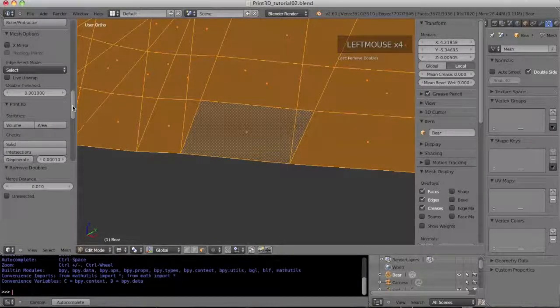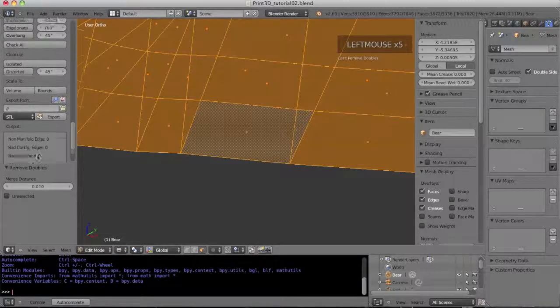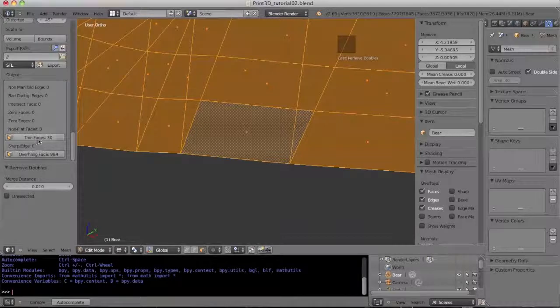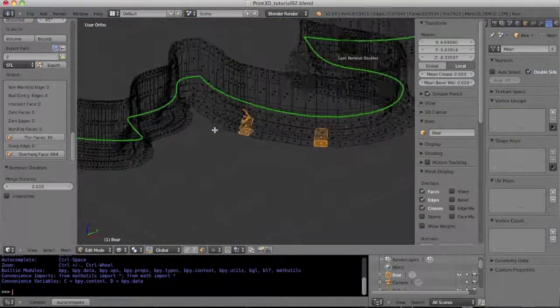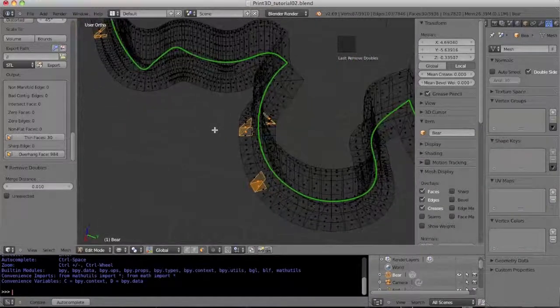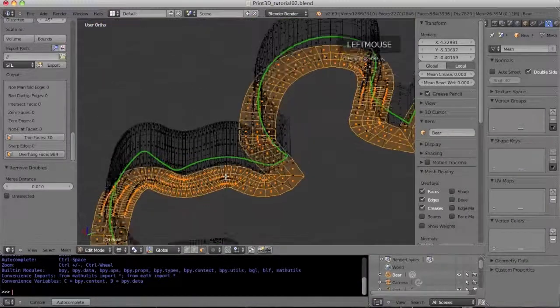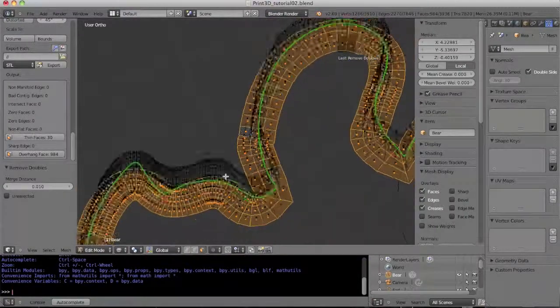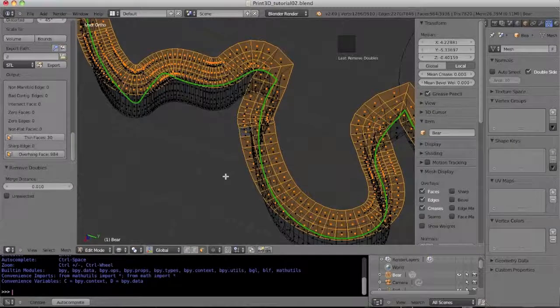So now check all. We got rid of some, but not all. So for the time being, I will just leave it that way. Now these overhang faces are actually the base faces of our cookie cutter outline, so that's not a problem at all, because that will be on the printer's bed.